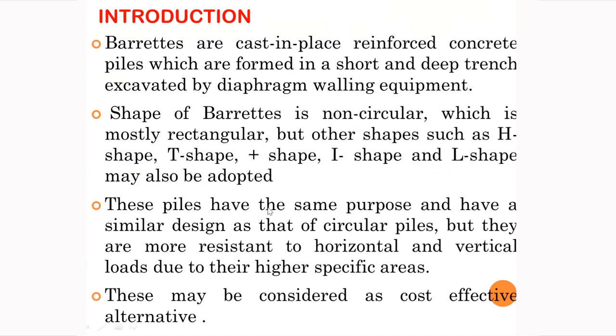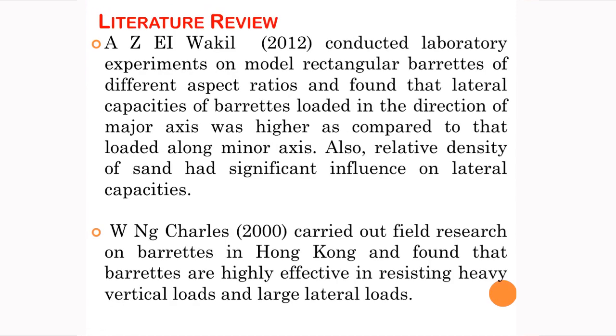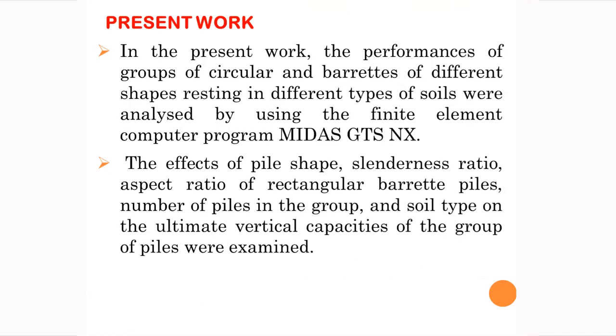And these piles can be designed exactly as circular piles. However, they have greater horizontal and vertical capacities due to their higher specific areas, and this may lead to economy. In the literature, experimental work as well as field work has been carried out, and they have found that these barrettes are very effective in resisting lateral load, and that's why they can be adopted in the field where it is required to resist a very high vertical or lateral load.